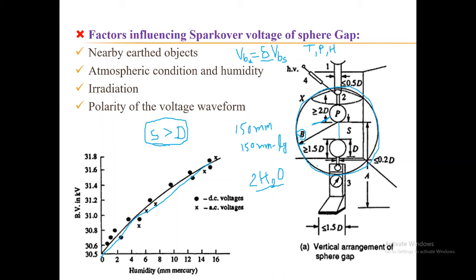So in that case, first we can observe the development of the corona discharge, and then successively the breakdown appears. So in case of this non-uniform field gap, if I change the polarity, the negative breakdown voltage value which I get is more than the positive value. Let me explain how this happens. Let me first wipe this out.